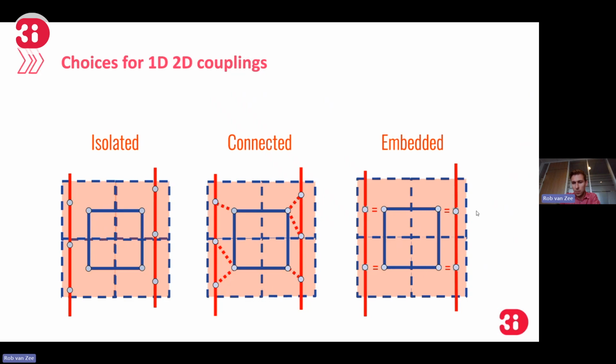So you also have the same water levels. And what actually happens is that you don't have two different calculation points anymore, but you only have one point where the water level is located. And you use this, for example, when you have very small 1D elements that you can't capture in your digital elevation model. And then you can embed very small elements and still have some hydrodynamic processes in your model.